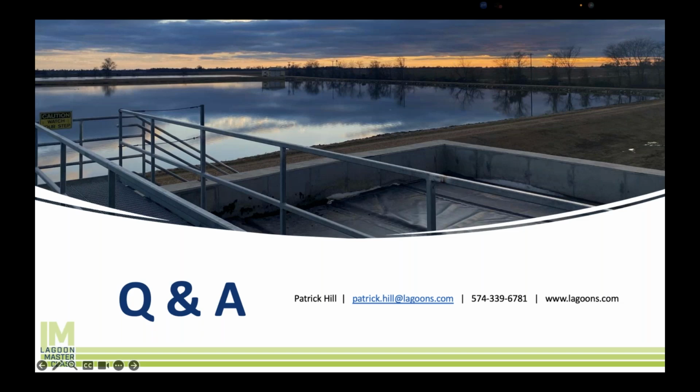Duckweed floats, so if you have your effluent pipe 2 feet below where the duckweed's floating, you shouldn't suck any duckweed into it. Largely speaking, you shouldn't. And I've seen that a bunch.